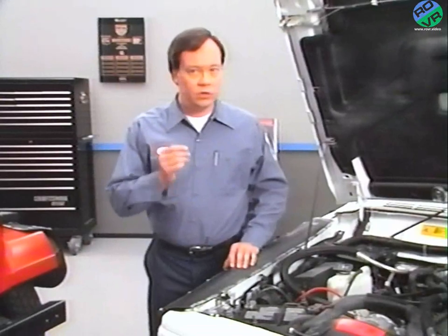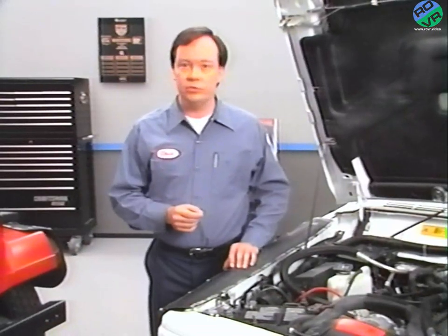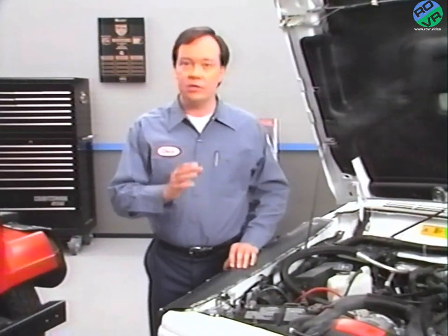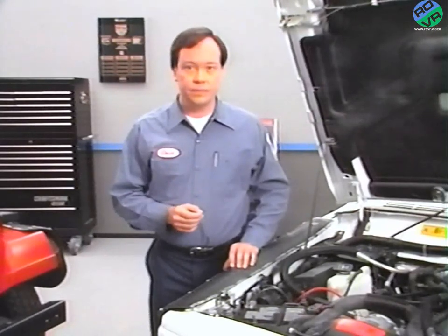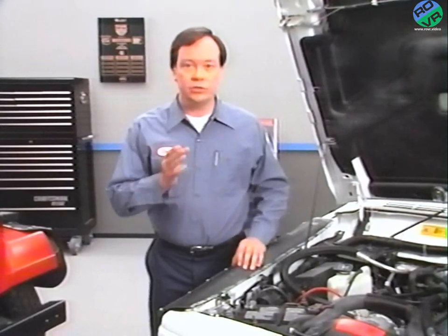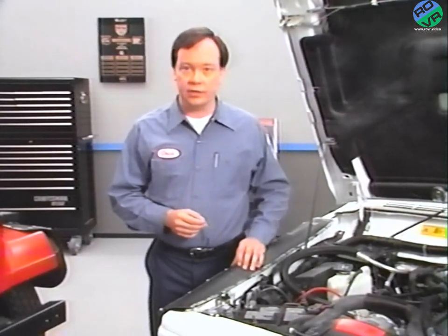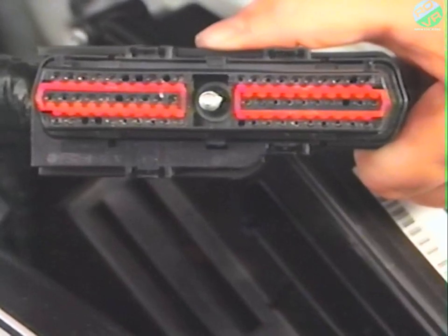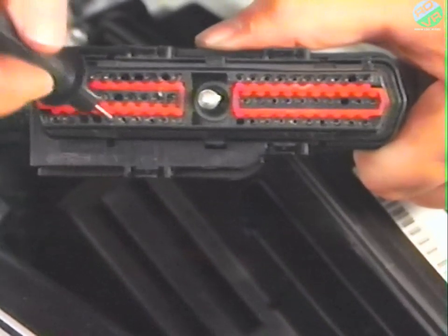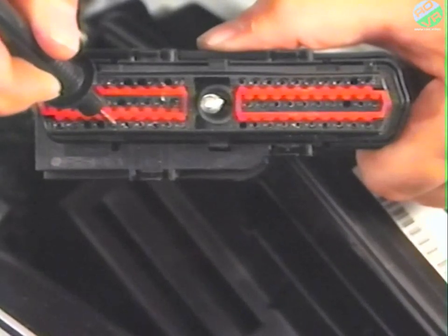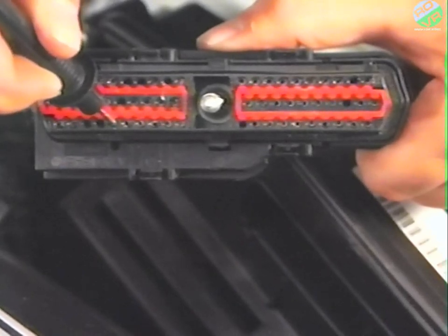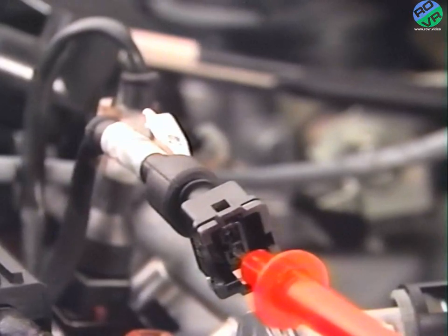But if, when you first probed the white wire with dark blue tracer, the resistance was higher than 10 ohms, you need to check the control circuit for an open. To do this, you should disconnect the engine controller connector and use an external ohm meter to check the resistance of the wiring harness between the engine controller connector and the injector connector by probing terminal number 16 of the engine controller connector and the white wire with dark blue tracer.